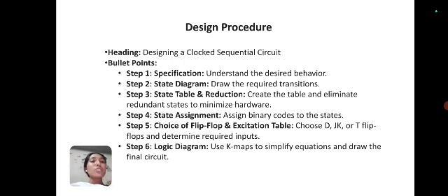Step 5: choose the flip-flop. Choose D, JK or T flip-flop. Determine the required inputs. Step 6: logic diagram. Use K-maps to simplify the equations and draw the final circuit.